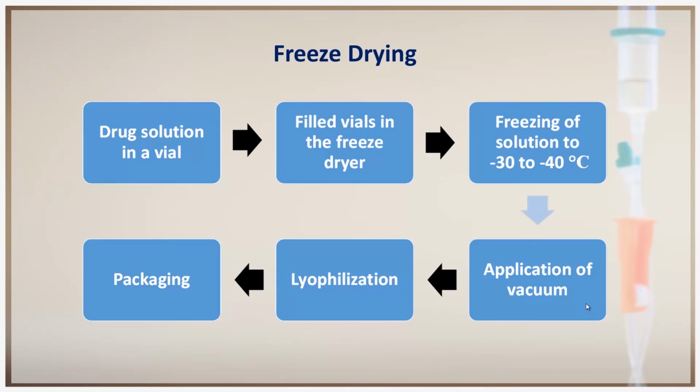In the whole process of freeze drying, the critical quality attributes should be taken care of. These include dissolution, appropriate residual moisture level and acceptable cake appearance. In addition, the process conditions should be those that minimize the drying time without adversely affecting the product quality. So this is the third method for the preparation of dry powders.